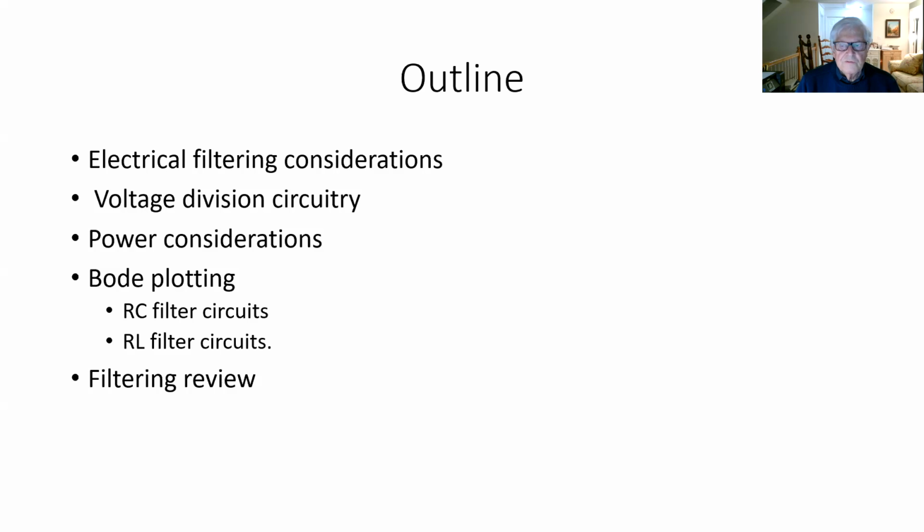We're doing voltage division to get a voltage output, and that output will be filtered. It'll be just the stuff that we really want, whether it be low frequency stuff or high frequency stuff, or possibly a particular frequency, just a very small frequency range.